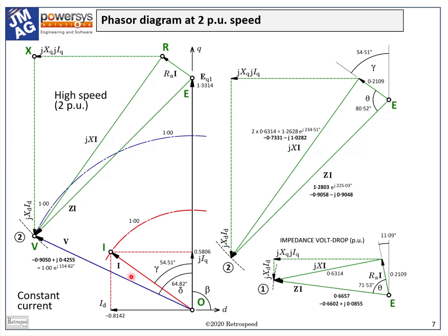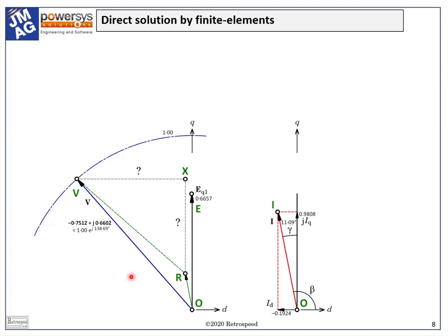The equations behind the phasor diagram are quite simple, and it's often possible to solve for the required angle gamma even with a closed form solution when the parameters are known. However, there is a point of profound importance to be made. The phasor diagram appears to rely on superposition. The voltage phasors or vectors are added together apparently without stopping to consider whether this is valid under saturated conditions. Under saturated conditions, the magnetic circuit is non-linear, and superposition cannot be expected to apply.